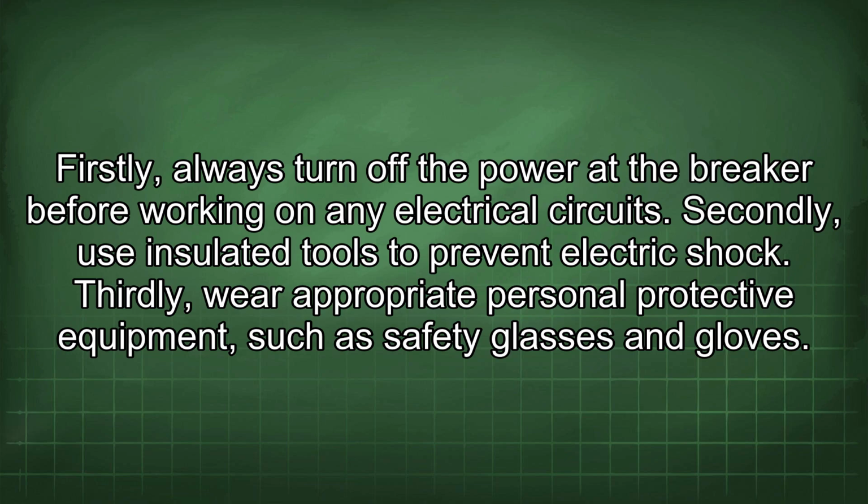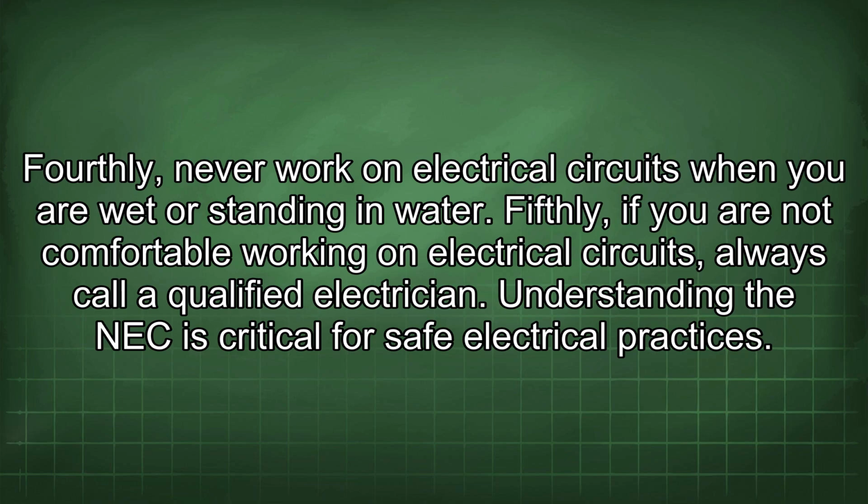Firstly, always turn off the power at the breaker before working on any electrical circuits. Secondly, use insulated tools to prevent electric shock. Thirdly, wear appropriate personal protective equipment, such as safety glasses and gloves. Fourthly, never work on electrical circuits when you are wet or standing in water. Fifthly, if you are not comfortable working on electrical circuits, always call a qualified electrician.